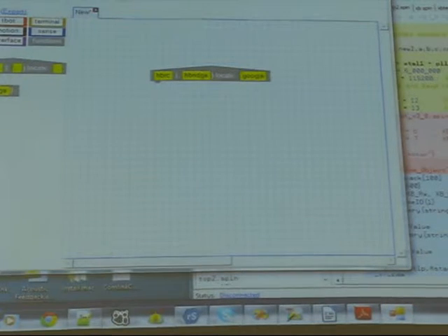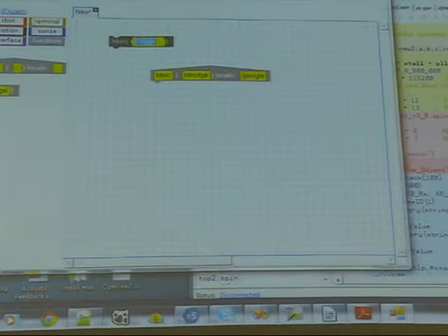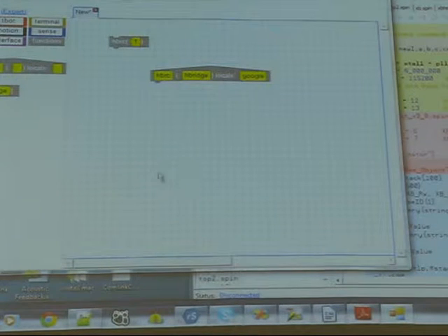And then this creates a caller block that looks like this. And so in this case, I pass a value of 1 into the function, and then an h-bridge uses that. But normally, everything is a global variable, and global across all the processors. And the Propeller guarantees that writing to those variables is atomic. So you write the variable and it gets that value. Obviously, if you have multiple processors writing different values to the same variable, then you have issues. And so then you talk about locks.